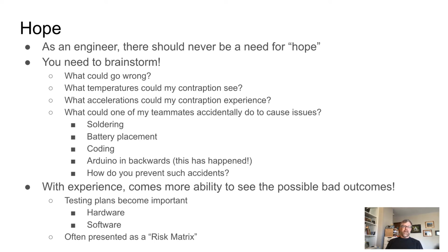So like soldering, battery placement. If you put a battery on something and then you start shaking it around, could the battery just pop loose? That could cause issues. Coding, there's lots of coding issues. Could you actually make a mistake and allocate memory every time you go through a loop, and then it just grows and grows and grows and eventually just stops working because it has sucked up all the memory in the system.